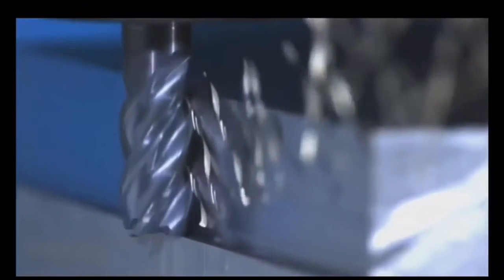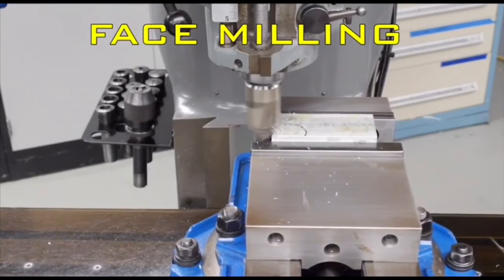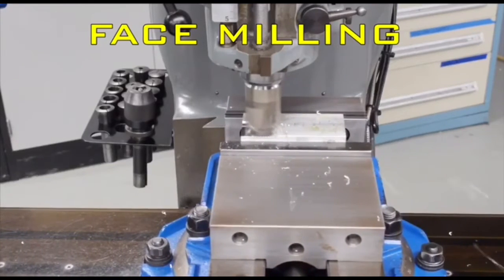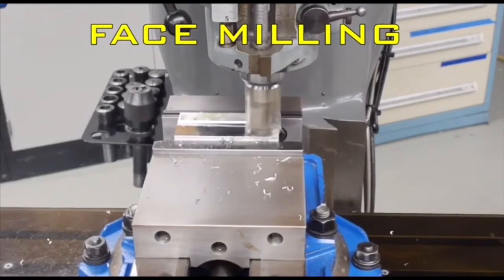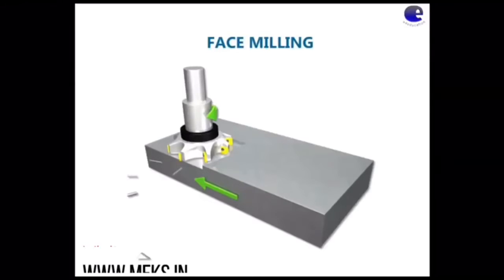Actually, there are many types of milling process, but for this case, I only take two types of milling, which is face milling and end milling. First, in face milling, the cutter is mounted on a spindle having an axis of rotation perpendicular to the workpiece surface. As the relative motion between the cutter teeth and the workpiece, face milling leaves feed marks on the machined surface.